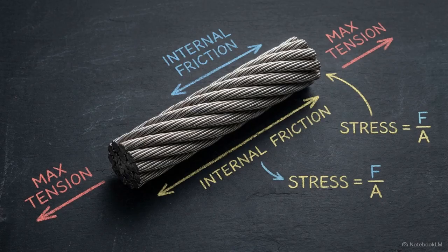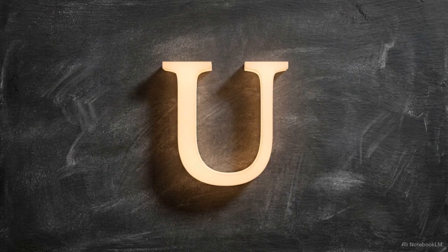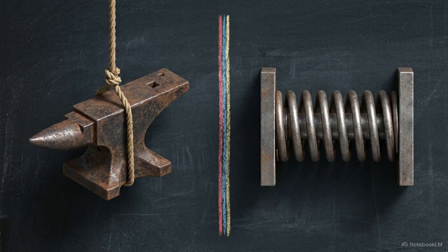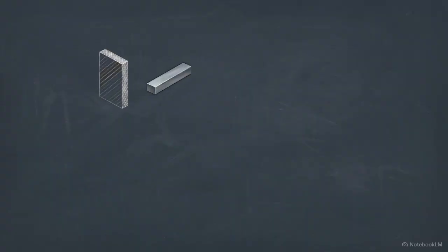We then shift focus from the external movement of the structure to the internal resistance occurring within the material itself. This is the second component of the Hamilton functional, potential energy, denoted by U. While basic physics often focuses on gravitational potential, the mechanics of materials focuses on an internal energy state. In this context, potential energy is elastic strain energy.